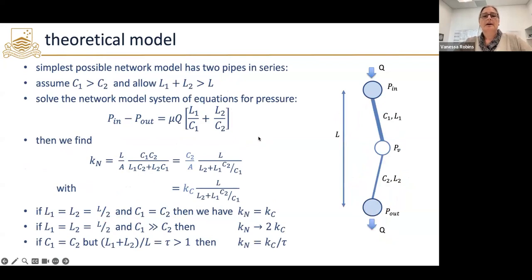So this was where I got to put on my theoretical physics hat and start with the most simple toy model possible and do a little analytic scaling analysis. So now we're going to imagine our network model consists of just 3 pores and 2 pipes, yeah? And if I set that up, I've got a very simple 3x3 linear system, and I can calculate exactly what that solution has to be. And we see that the pressure difference is equal to length on capacity for the first pipe plus the length on capacity of the second one, yeah?